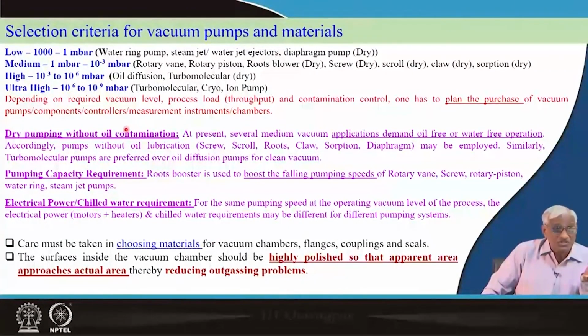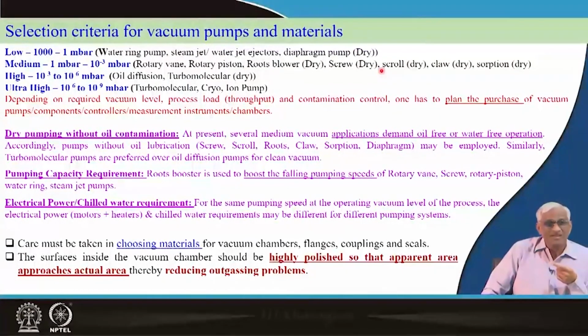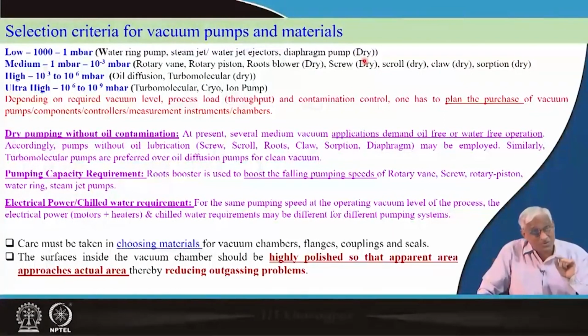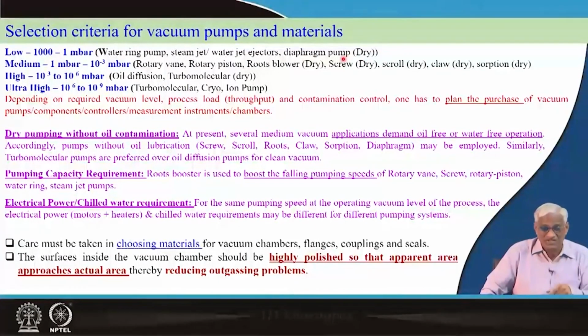And now in automation issues, IoT issues, you have to be equally good in selecting IoT related things. So, first pump, depending on the range you will have varieties of pumps available. Then you will have to take which one? One is pumping speed at the pressure at which the process is operating, not just pumping speed, but what? Pumping speed variation.